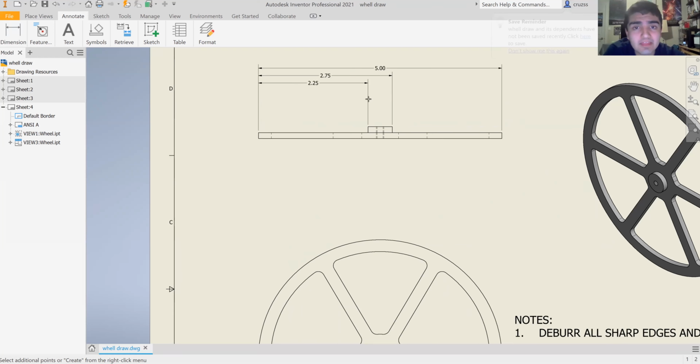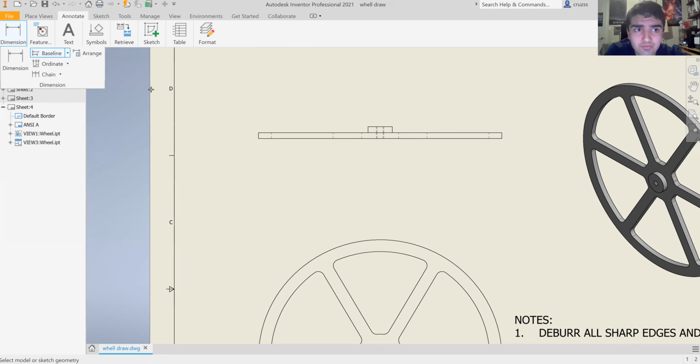So keep in mind that if you're someone who's going to manufacture this, unless this is being 3D printed, chances are you want to be very specific about how you have these items done and labeled. Now, if you're going to 3D print this, ultimately the computer generates all that information. You already have everything you need if you have an STL file of this. So that's not going to be that important. Obviously it's still good to have these habits, and you're going to want to make sure that you have all the information that would be important to manufacture anyway, just as a good force of habit.